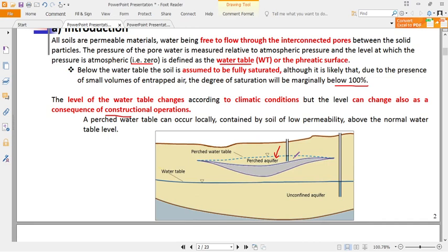Therefore, it's very important to do what we call a pump test. When you are looking for water for supply through boreholing, or through groundwater supply, you need what we call a pump test. You do it for 3 days, pumping water to see if there is a yield from the well, to see if the water comes back into the well. If water doesn't come back that way, it means that one may have a perched aquifer. Okay.